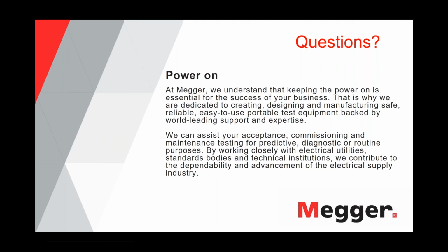But as Javier explained, the phase shift between the voltage and the current is only defined with a sinusoidal waveform. So if you have this cosine rectangular waveform, this is not defined in the same way as it is for the sinusoidal wave. So it's kind of exclusive. If you want to measure leakage current, you need the cosine rectangular waveform. If you need to measure tan delta, you need a sinusoidal output on your test set as well.